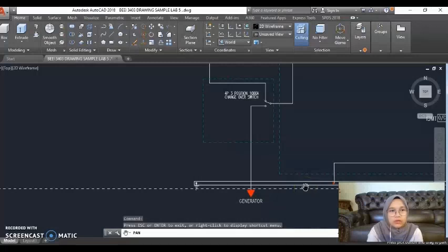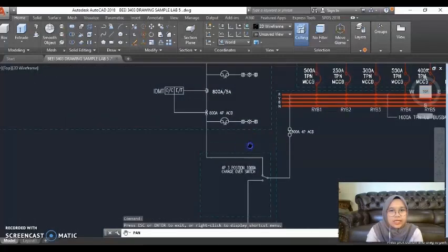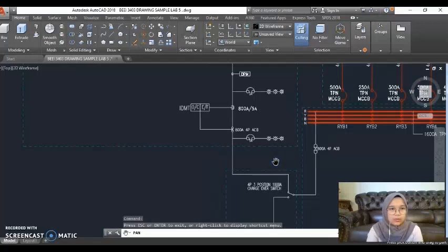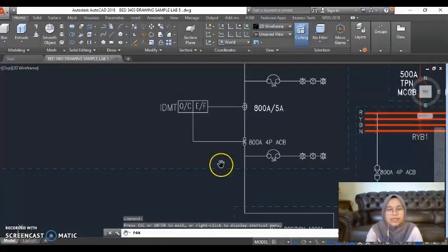through an auto changeover switch. Firstly, from this generator, the power flows through the 4-pole 3-position changeover switch. The rating for the changeover switch is 1000 ampere. Then, as you can see here, there are red, yellow, blue lamps. These are indicator lights with rating MCB 5 ampere.